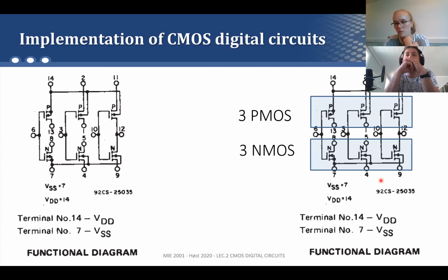There is important information here. One important thing is that the power supply of this integrated circuit has to be connected all the time to pin 14, which is this one here. And the ground, which here is called VSS, has to be connected to pin 7.